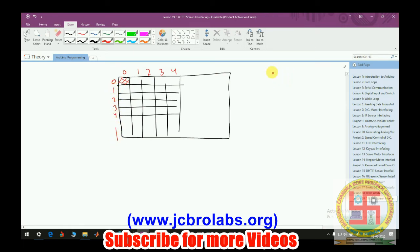So if we have our LCD as 128 cross 160, this is the X size, and this is the Y direction. So 128 cross 160 means it has 128 rows, so it will go up to 127, and it will have 159 columns. This is how each LCD pixel is represented. When we are talking about 0, 0, it represents this pixel. 0, 1 will represent this pixel.